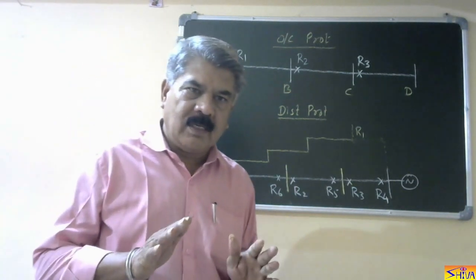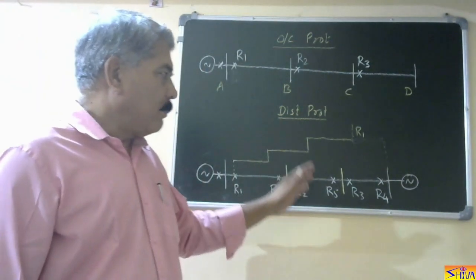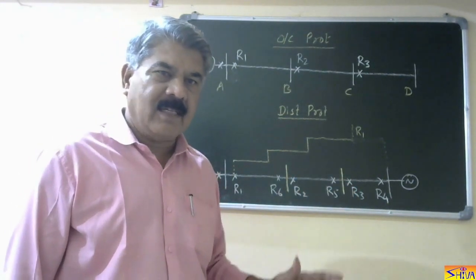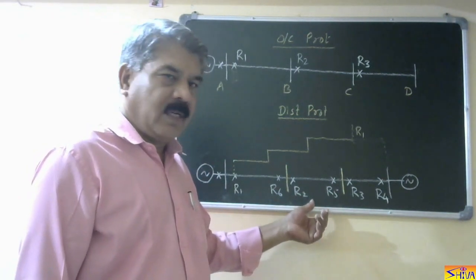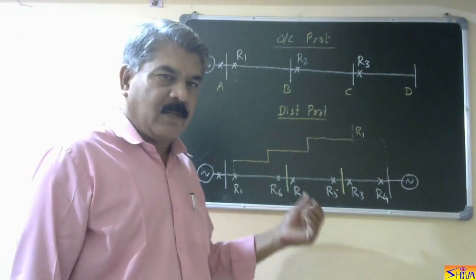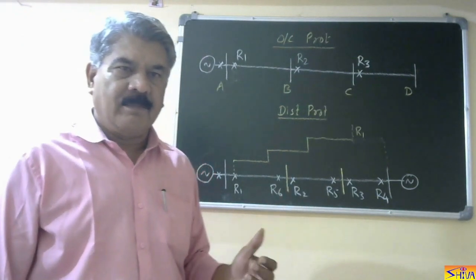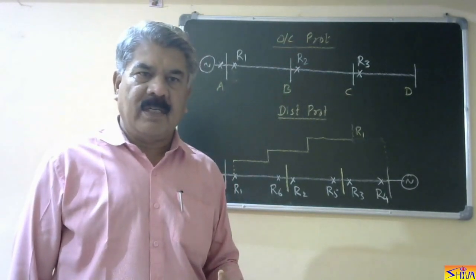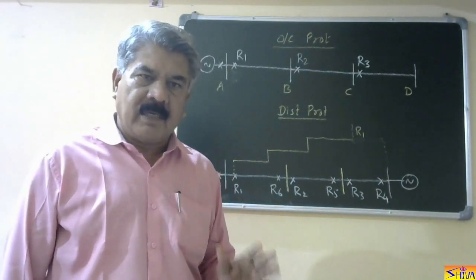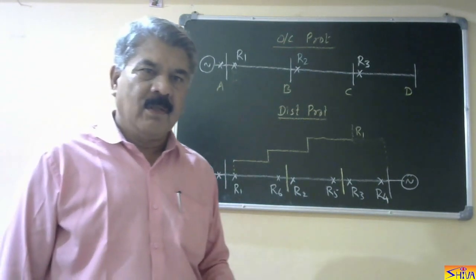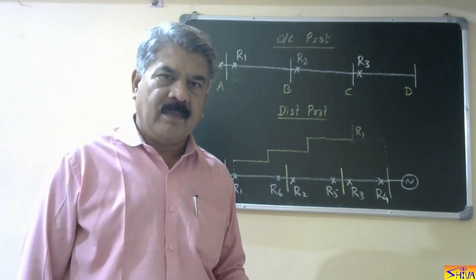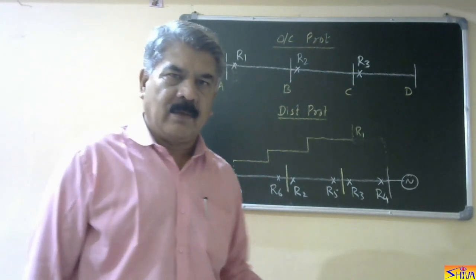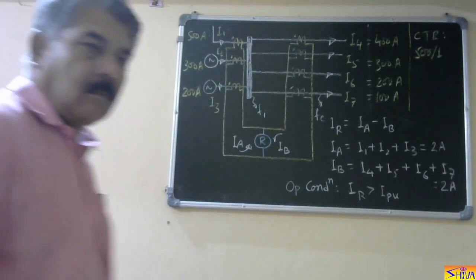So our conclusion can be like this: we don't need separate bus protection as it is covered in the line protection or backup protection of generator and transformer. In old days, when fault level was not so high, separate bus protection was not essential. But nowadays, fault level is very high, so we need separate bus protection. And that bus protection is provided by using the differential relays that I will explain now.